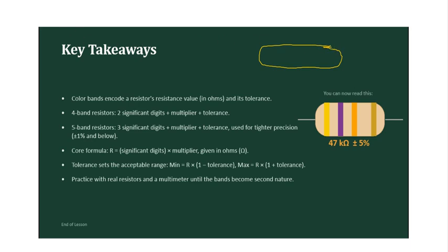And then you still have your yellow as the first color band, and then violet, this is not very clear, and then maybe orange, and like that. So what I'm saying here is that if you have a resistor that is bigger in size than this, but has this exact color band, it is still going to be 47 kilo ohm. The only difference now is that since it's bigger, the power rating is going to be more.